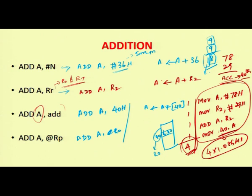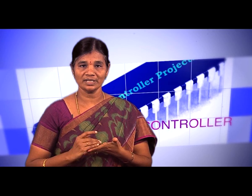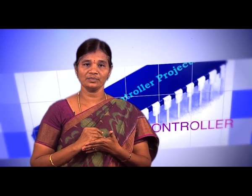So, we have one of the special function registers, which is PSW, the program status word, an 8 bit word. Okay. It gives the status of the arithmetic and logical operations. So, if after addition any carry is set, it indicates that the size is exceeded. The accumulator is an 8 bit register, it can hold only an 8 bit value. If the result is 9 bits, then the 9th bit is considered as a carry.